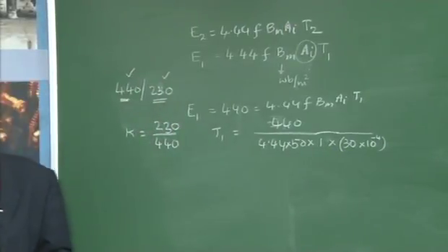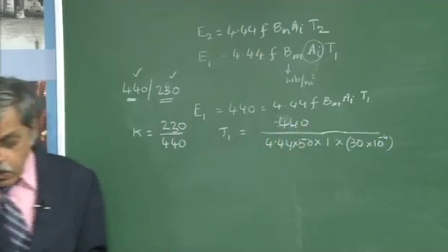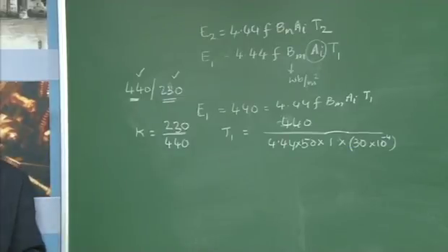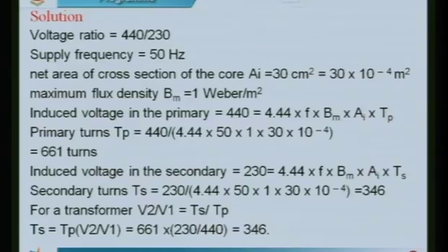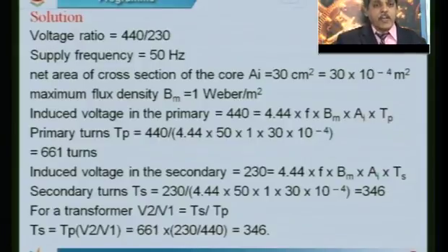Now definitely the ratio of these two will not give us an integer value. For the final value I have given here, it is not an integer. I have just given an integer here, but you never get an integer. So what you need to do is round it off to the next higher integer. Always the number of turns, see, I cannot have 22.5 turns.